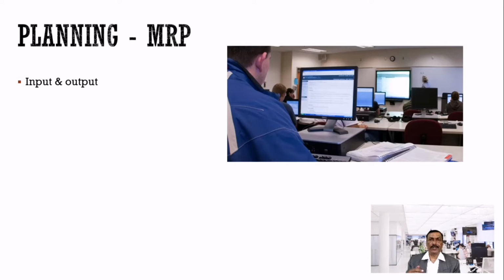It is usually done by the design team and it is available in the ERP. So in the MRP process, it checks what components are required for manufacturing a product. Then it also checks what inventory is available in hand and what we have already ordered from the vendor, what balance is expected, and it does some type of netting.